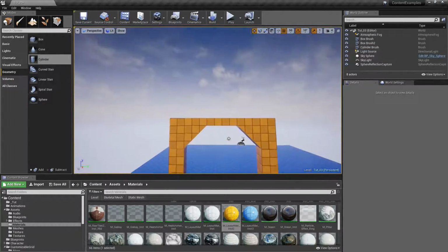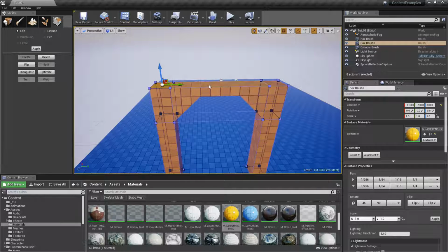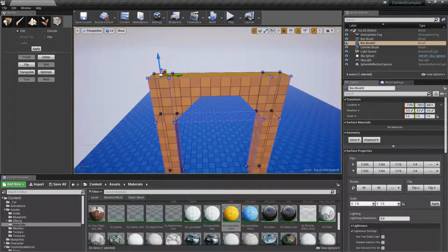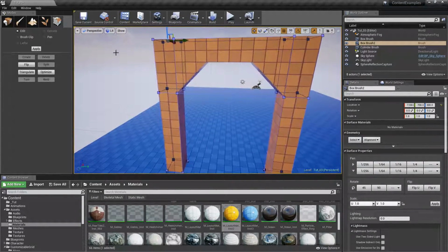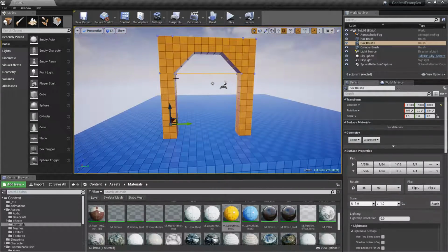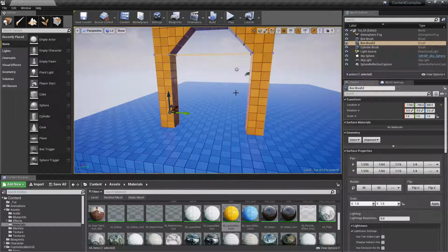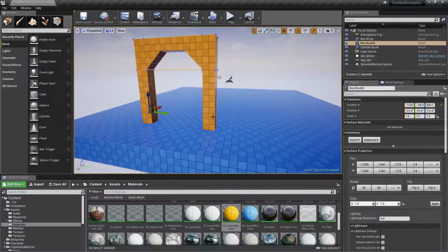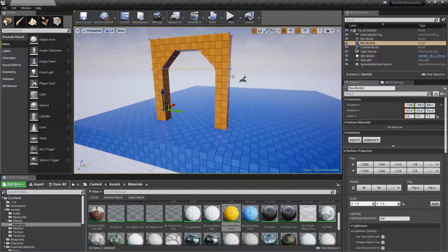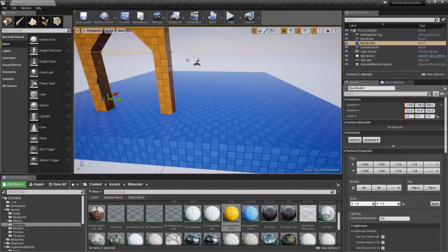To be honest, I think this should also go a bit further up, so you can select with Control select, not Shift select, if you want to select multiple. And there we go. You have another doorway that's a bit more optimal than the previous one that we made, because we're using 2 brushes to make it. We used to use 3 brushes to punch the hole down here. But guys, there is an even better way to make this. You can make this with just 1 brush.